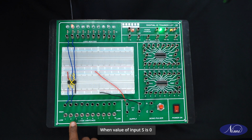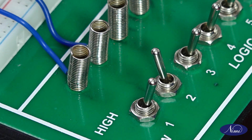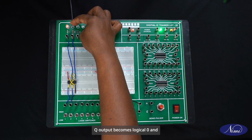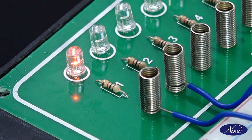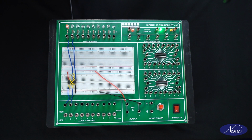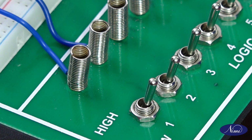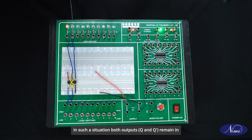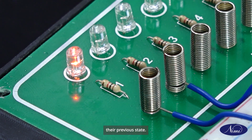When value of input S is 0 and value of input R is 1, Q output becomes logical 0 and Q bar goes to 1. Such a state of flip-flop is called reset condition. When both inputs S and R are 0, in such a situation both outputs Q and Q bar remain in their previous state. Now there is no change in the output.